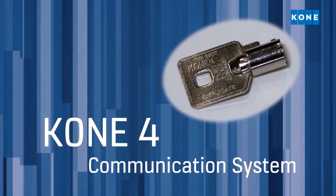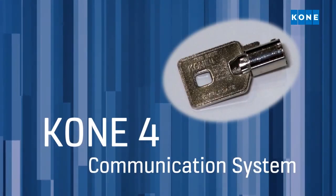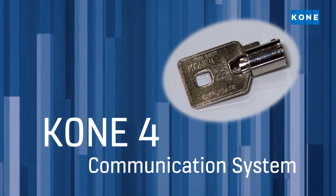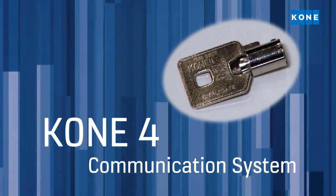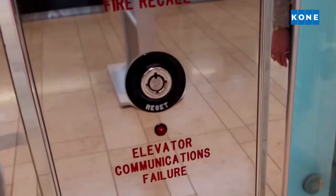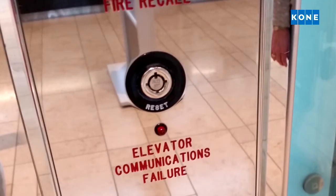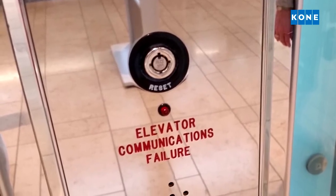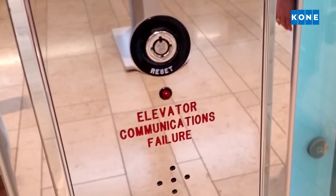The KONE 4 key is used to inspect your elevator's two-way communication system. The current elevator code requires that your elevator be equipped with an elevator communication failure device. This device is located in the vicinity of the fire recall key switch on the main egress landing of the elevator and is labeled Elevator Communication Failure.